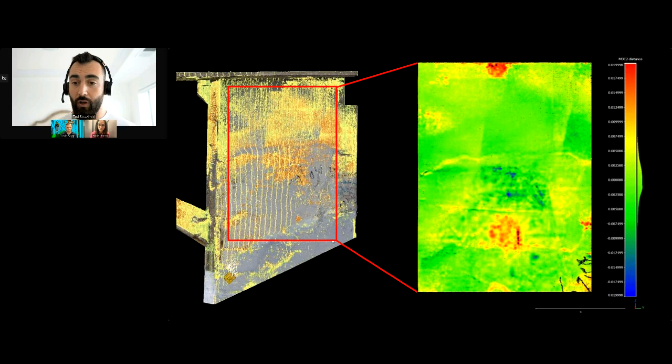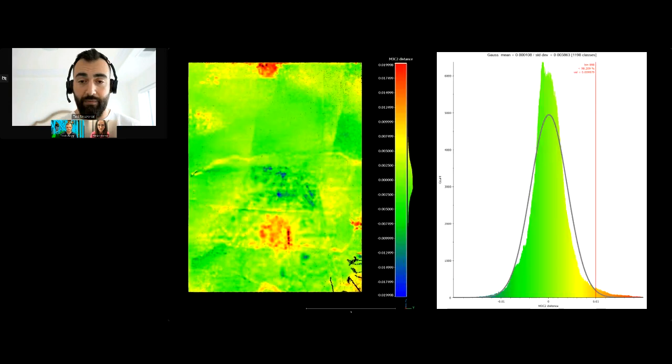So overall, it fits quite well, but there are some areas where photogrammetry may have its own registration errors, based on where those cameras were when they were taken, right? So there is a little bit of deviation there. And looking at the distribution of those distances across this area, you see that the distribution is quite tight. We have a mean of, what is that? Looks like just under a millimeter. Very close for the most part.